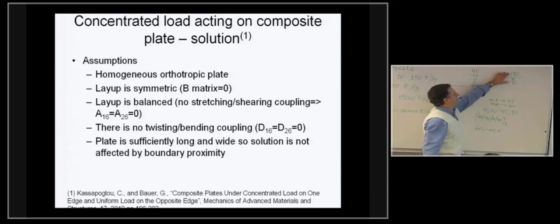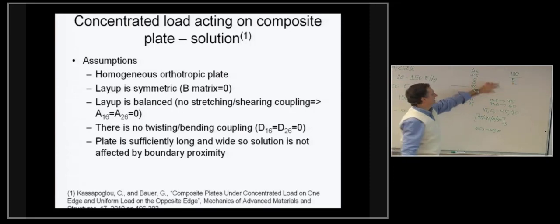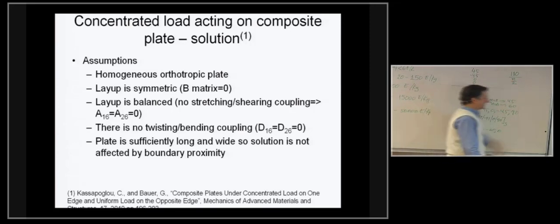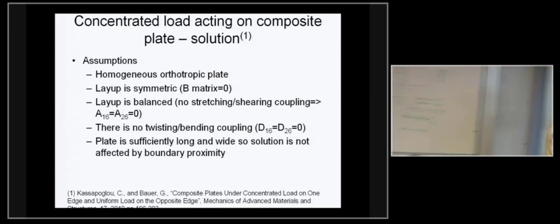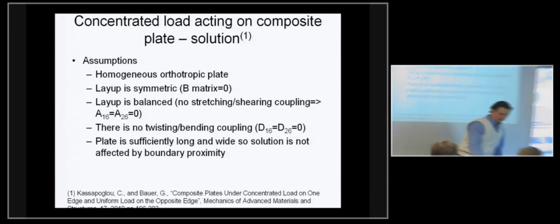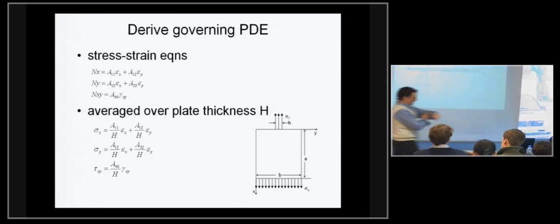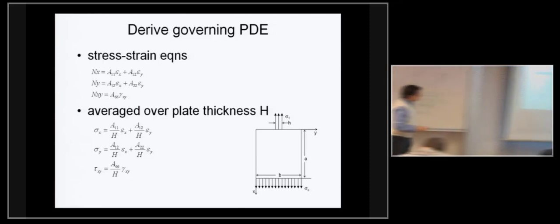And if you're trying to think where I got this, 2 times 180 is 360. So I'm taking the full circle of going around, and I'm making sure that I divide it in equal intervals, and I have fibers in those equal intervals, which is the same. That's where this comes from. So that was just a parenthesis, because I keep mentioning quasi-isotropic, and I meant to say that's one way of creating quasi-isotropic laminates. Stress-strain equations.